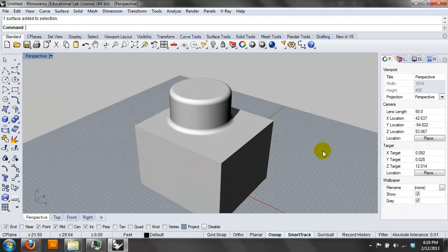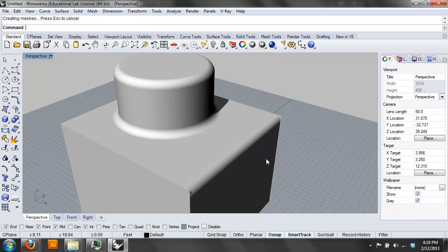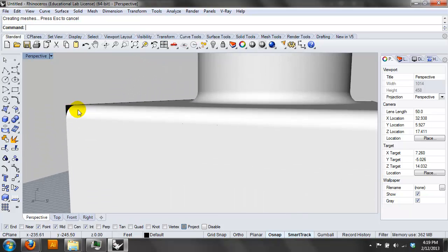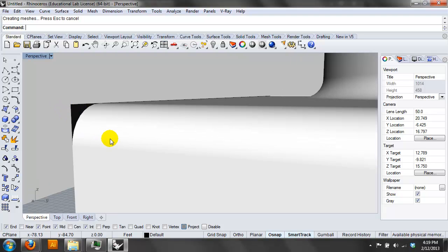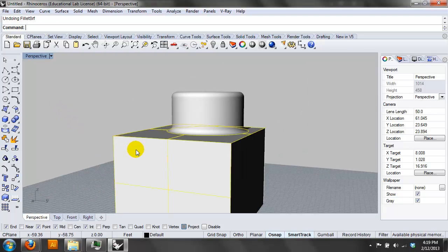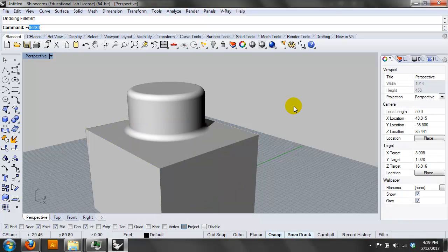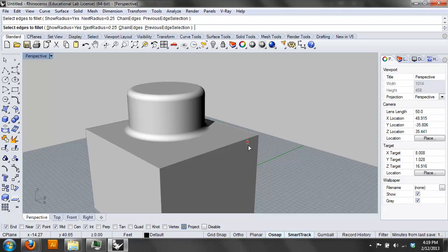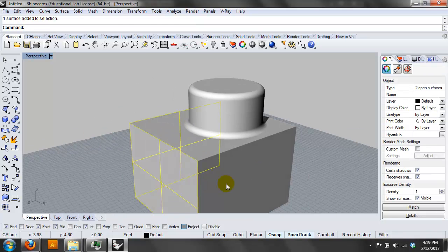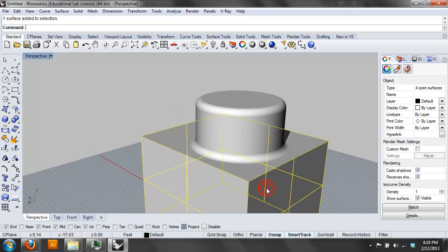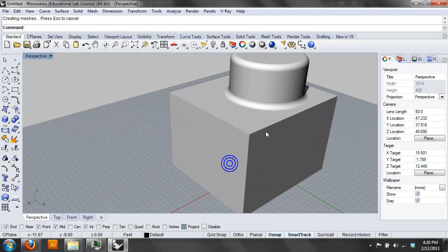So you want to do a fillet surface? So I do this. Okay, that does one, but then what happens? Fillet edge. Okay. So fillet edge, right? Oh, we can't because those don't even have edges. We could try to join these together. It does, but it doesn't show up in the render though.